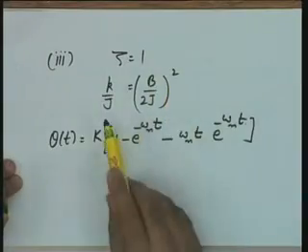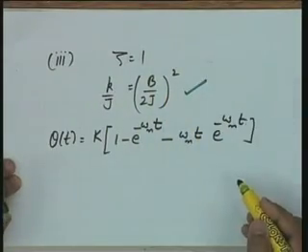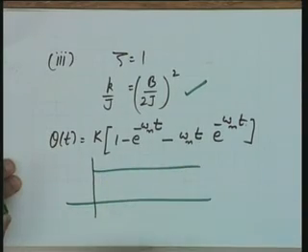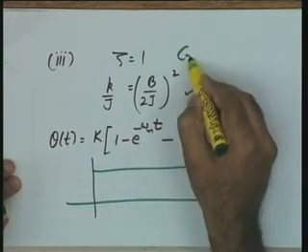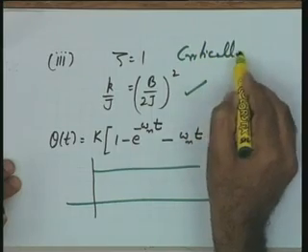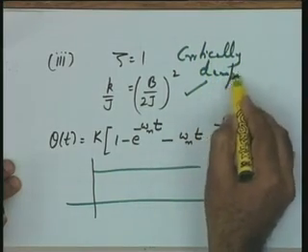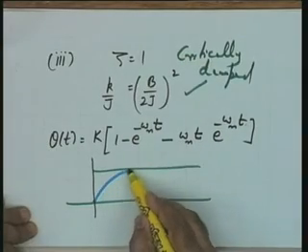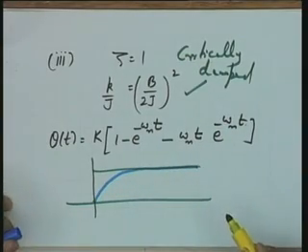Okay. One more slide I would quickly like to give you over here. The third case is zeta equal to 1. This corresponds to this K by J expression, this is the theta(t) expression. As you find, the underdamped case was the earlier one; this is the critically damped case, and in this particular case your response is just non-oscillatory, the oscillations have just been killed. The overdamped case is not accepted.